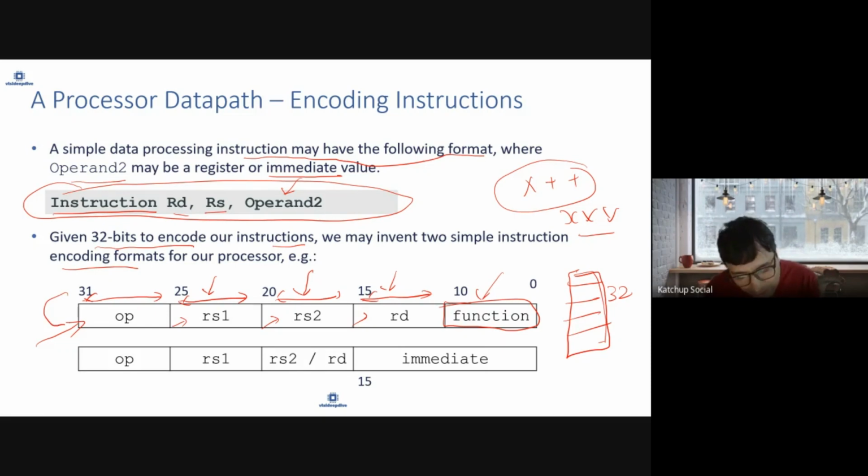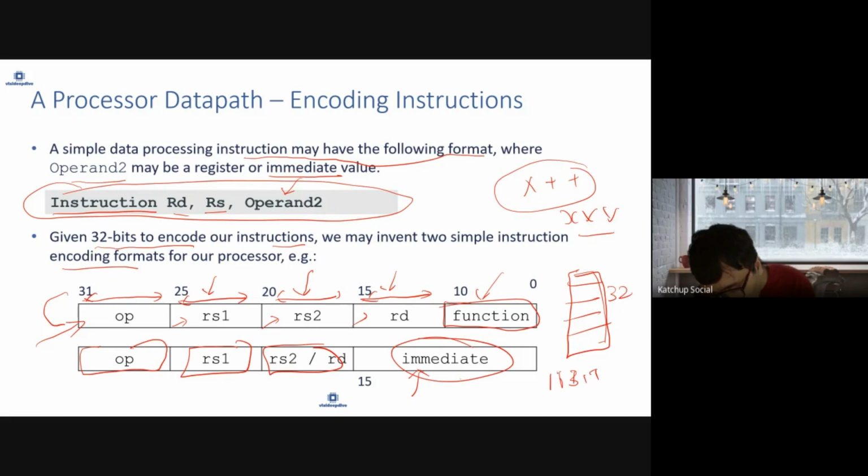If it's an immediate, we can have the opcode, the result, one operand, and then the second operand is the immediate. Please note this is 16-bit. Since our data size is 32-bit, this is only 16-bit, so we can only do a certain set of operations, and we have to make sure this data is converted to 32-bit when the operations are done, which we'll also design for.